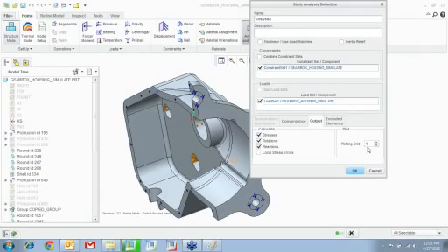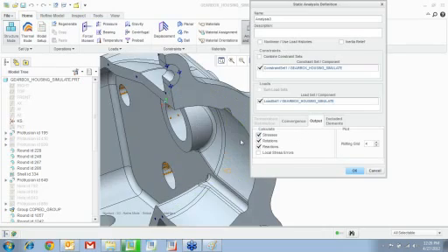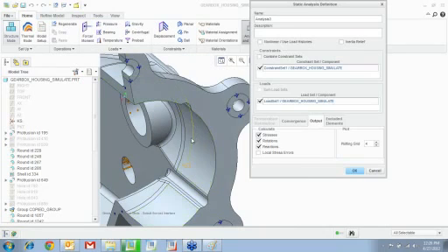Now personally, I prefer to leave it like that and change or refine the mesh locally. Now why do I want to do that? If you change the plotting grid, you're not changing the plotting grid for a certain area. You're changing the plotting grid for the entire mesh. Now that could increase the solution time. If I say I want more local results over here, I will just create a surface region over there, and then I can refine the mesh. And I'll show you an example of that.